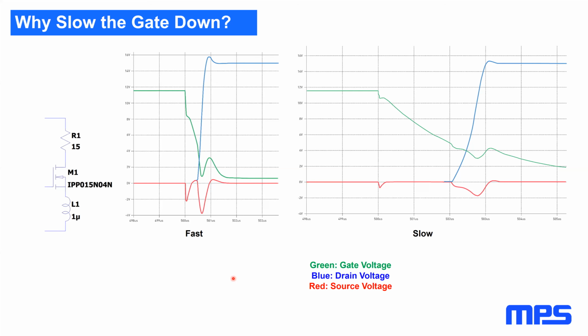Yeah, no, that's true. I mean, it again has to do with imperfect power supplies and bulk capacitance. If everything were perfect, then the drain wouldn't go much above the supply. Well, I shouldn't say that because with an inductive load, obviously it will.